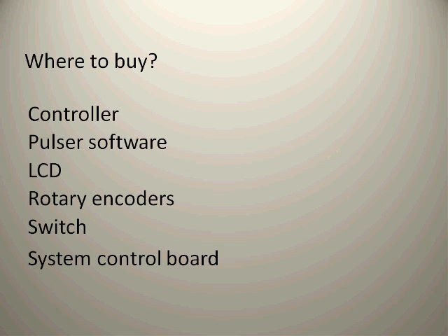This system control board is not mandatory, but it makes life easier because the connections needed to give a power supply to the controller and to connect the controller with the operational amplifier for PLL system signal amplification, for the LCD display and rotary knobs and some other components, it's easier to be realized using this system control board. They call it baseboard.